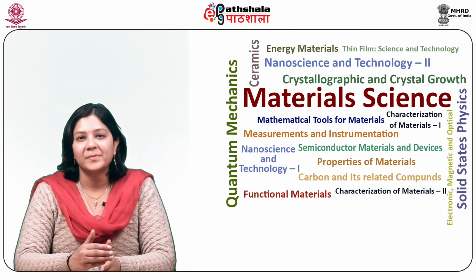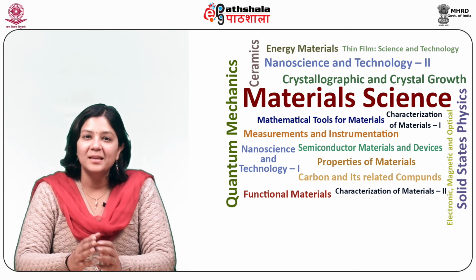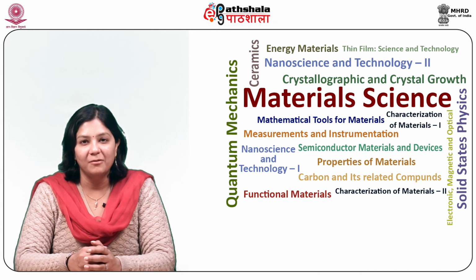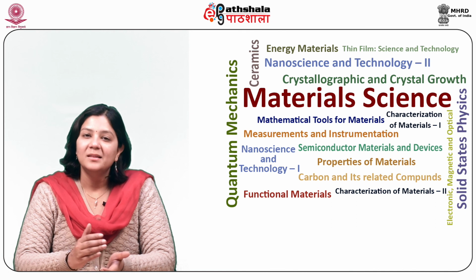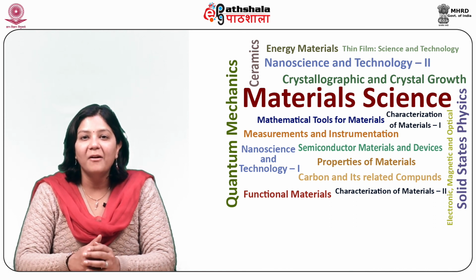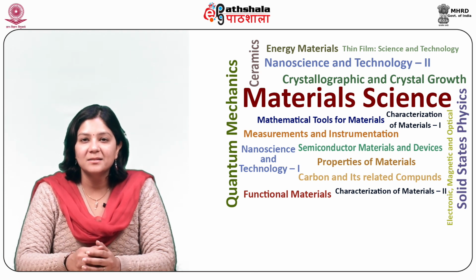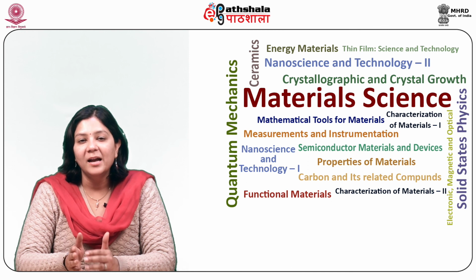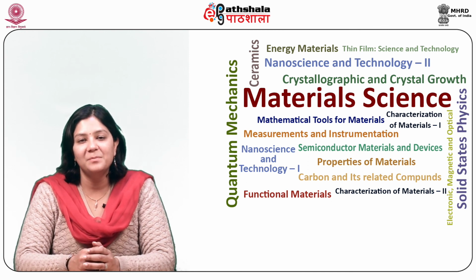Alloy scattering. It is the scattering produced by randomly positioned substitute atoms in the crystal sublattice of a compound or alloy semiconductor. This type of scattering only occurs in ternary or higher order alloys because their crystal structure often involves random positioning of some atoms in the crystal sublattice.